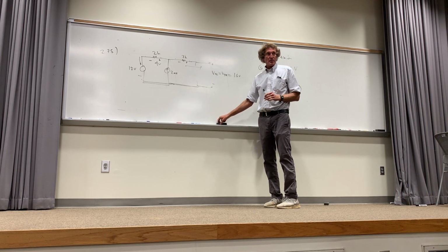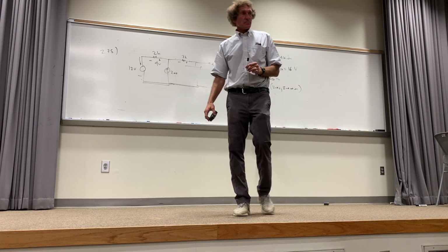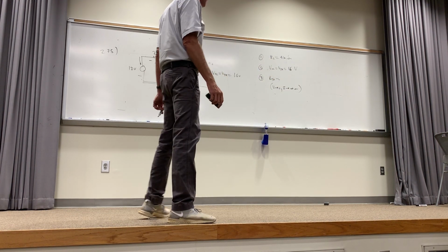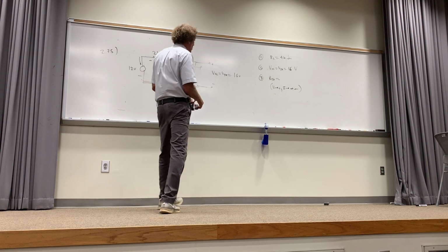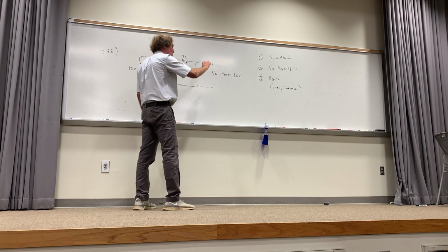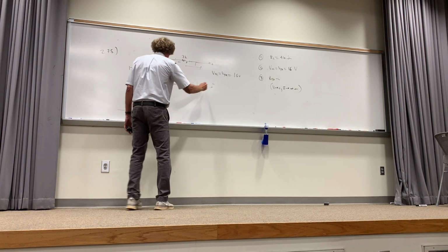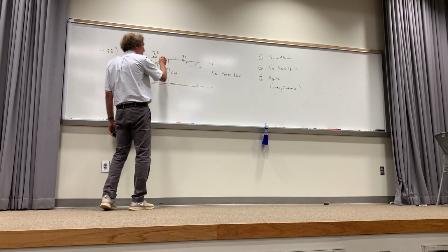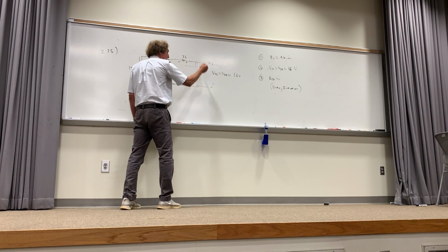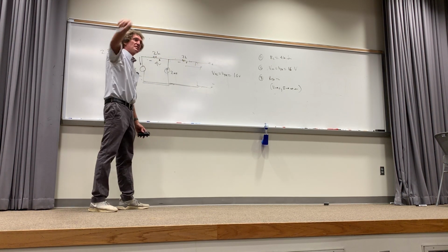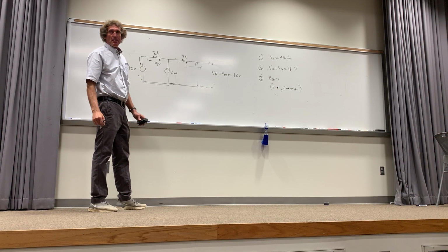Yes. I'm sorry. When you got the voltage, why did you go from the negative terminal to the positive terminal? Well, the way you always get voltages, we could write an equation for the loop voltage. We could start, here's the increase of 12, increase of 4, 0, and then decrease of VOC. But just take VOC to the other side and make it positive. Okay. All right, that's the reason.